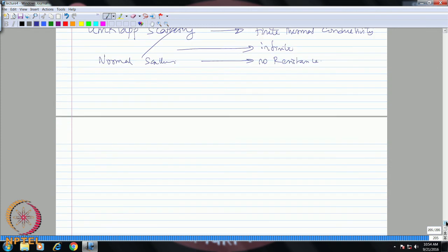Okay. So, now how do we calculate all these scattering modes? We have normal scattering, Umklapp scattering, phonon-impurity scattering, and phonon-boundary scattering. There are some standard expressions which I would like to give. For example, in the case of Umklapp scattering, the relaxation time has a particular empirical correlation which is like this.